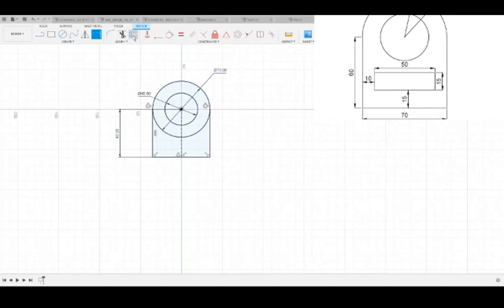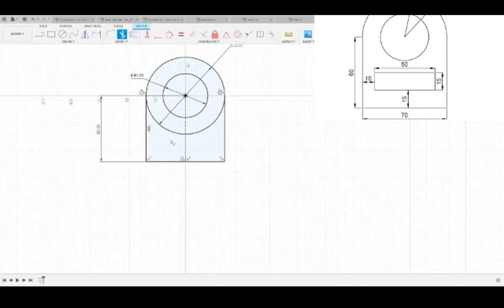we're going to remove that using the trim tool because I don't remember how to use arcs in Fusion, because I know that's a facet of the line, but I know there's a single thing you have to do to that. I don't remember. This is also equally as straightforward. So with the trim tool, you can just pop the trim to there, and the auto trim will detect what line sits between two sketch points and then remove it.